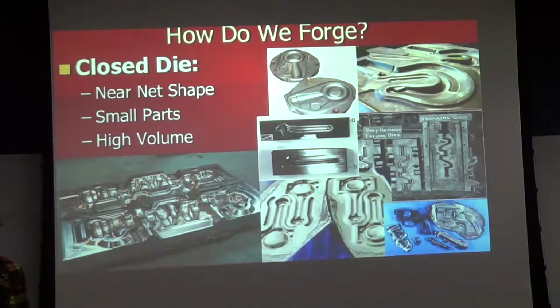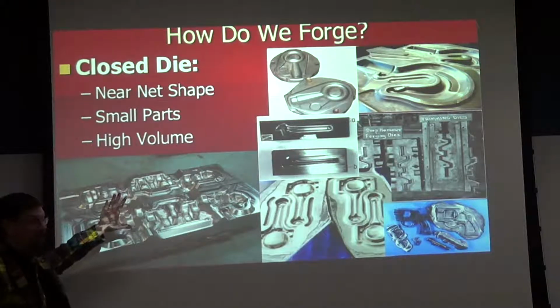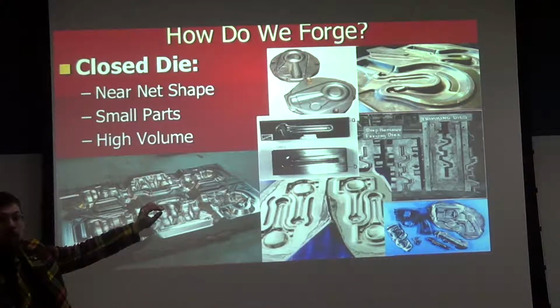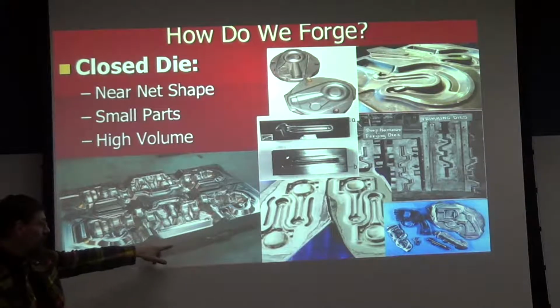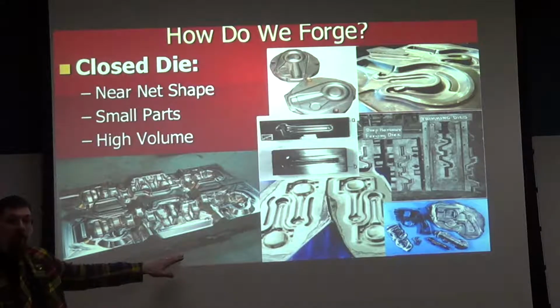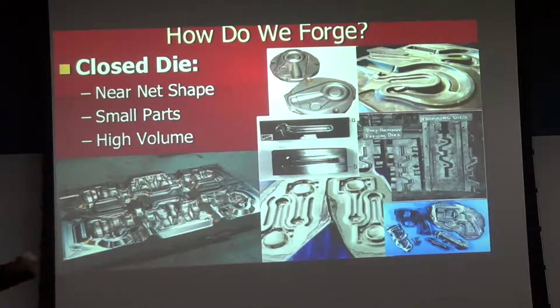So they'll just go and trim the top down a little bit, and then they can maybe do that again. I don't know how many times they can do that, but it depends on how thick the die block is. And if they get to a point where they can't do that, they can always machine this out completely, and then they can flood weld that back, so that they're at least preserving whatever machining they did on the back that anchors that into the machine.